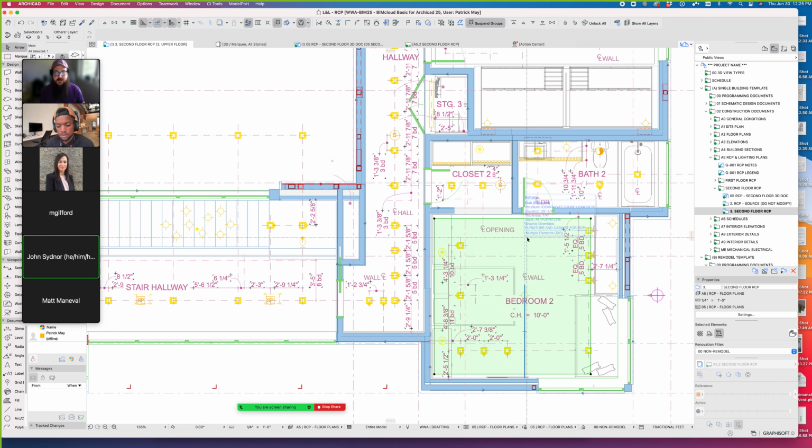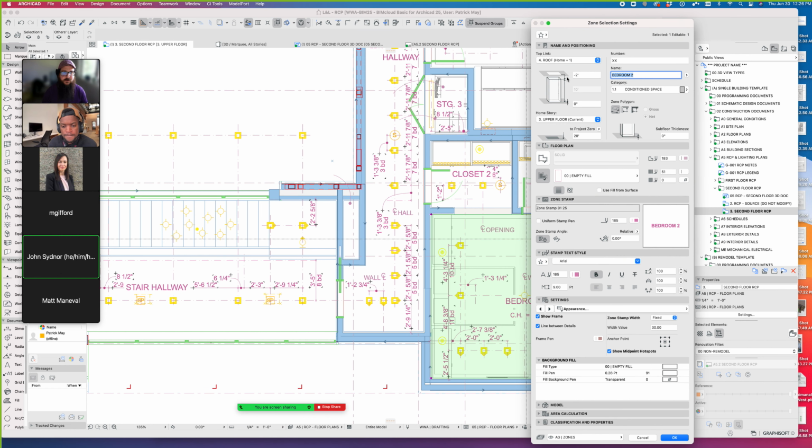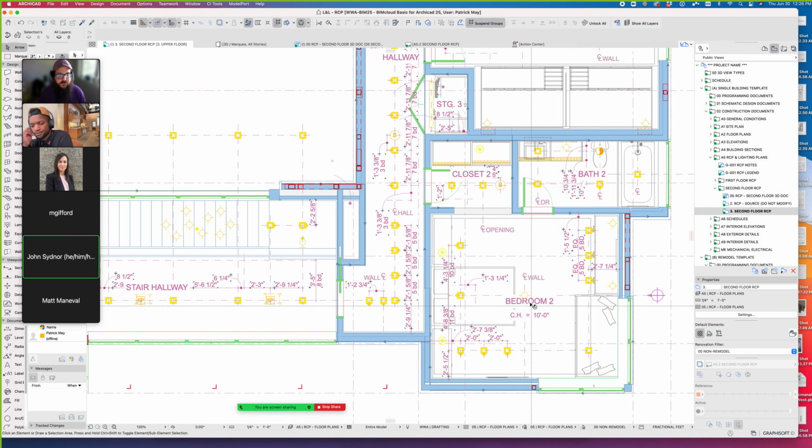They can be tied to the floor-to-floor height, but there's just so many times, I would say more times than not, that the ceiling does not match the floor-to-floor height, the story settings. It's like below the story settings by X number of feet. So understanding and knowing what those ceiling heights are is really important. Sometimes that just has to be manual text.